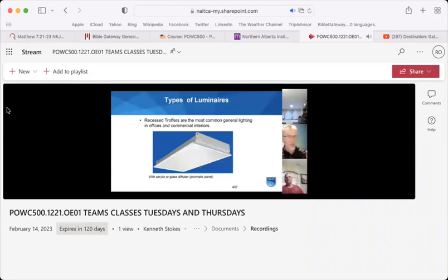So sort of your common, normal luminaire. We're not going to call this a light fixture anymore. We're going to remember that it's a luminaire. Looks like this. It's called a recessed troffer. Troffer refers to the ability for this to fit into a hanging ceiling. Hanging ceilings or suspended ceilings are very popular. They're very practical. They're able to suspend our lighting systems, give us a good light colored surface to spread the light around, and then the ability to get in behind there to change wiring and check on piping and move things around.